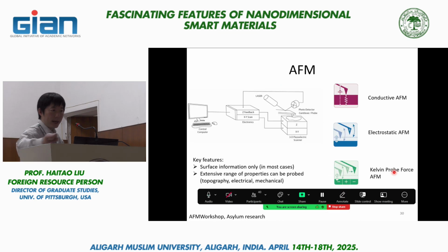And the last part, I want to talk about atomic force microscopy. Again, this is a highly versatile technique. How this works, you have essentially a needle. Think of my finger as a needle, and this needle vibrates because a piezo driver vibrates it at very high frequency, typically a couple hundred kilohertz. The experiment we do in our lab typically uses a tip that vibrates at about 300 kilohertz. Okay, so 300,000 vibrations per second.